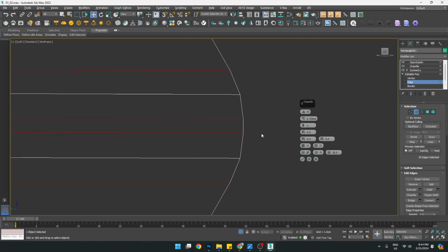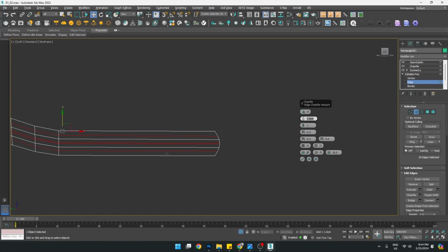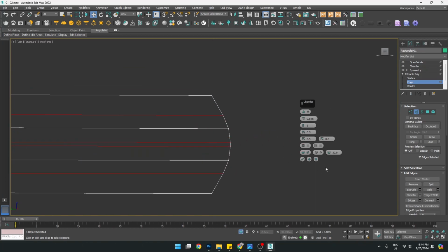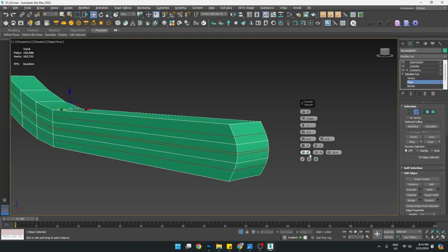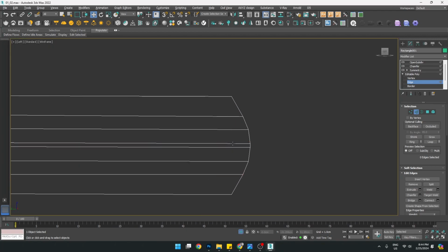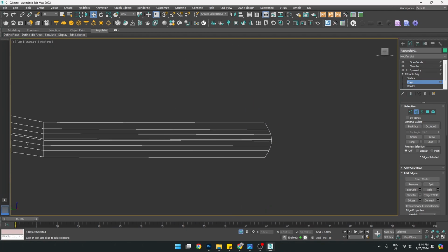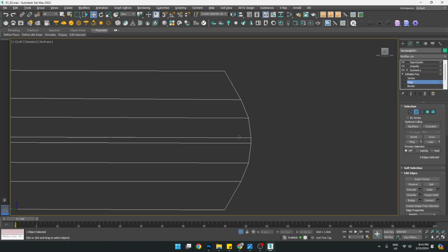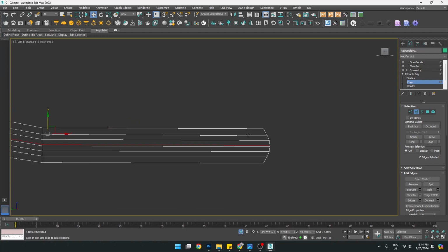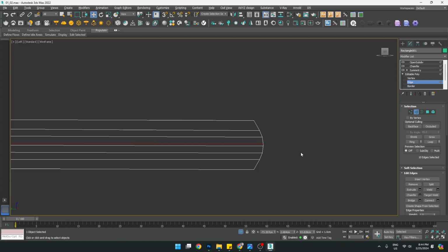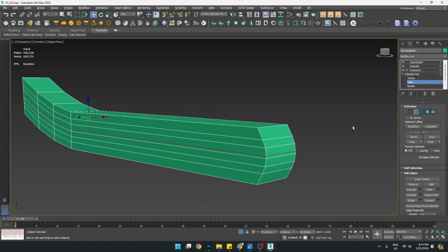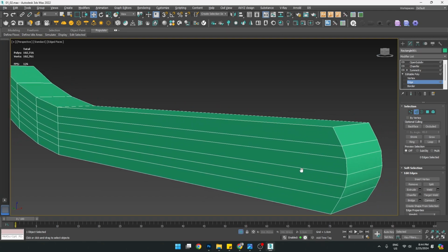So, okay, let's keep it at 0.8 and then we can probably delete one of the segments. Disable this chamfer smooth because we don't need that at the moment. Click on it and then deselect by clicking anywhere in the viewport, and then double click, press control and then backspace to remove that edge, that selection.